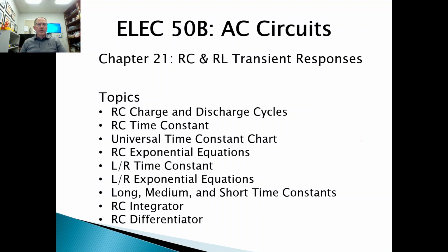And this week we're going to talk about chapter 21 and RC and RL transient responses. So the topics here are RC charge and discharge, RC time constant, the universal time constant chart, then the RC exponential equations, then the L over R, the inductance over the resistance, time constant, exponential equations, and then long, medium, short time constants, and then an integrator and a differentiator.